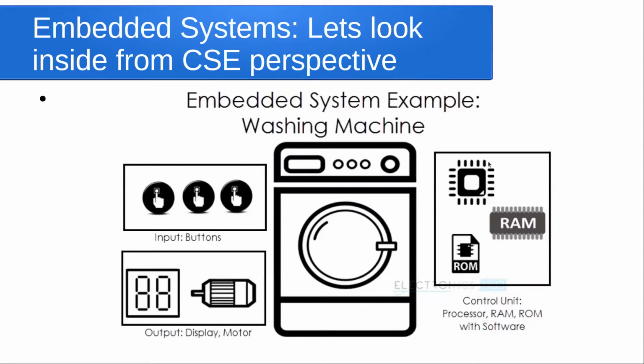Once these inputs are received, depending on the program selected, the processor's or microcontroller's output pins are connected to appropriate display or appropriate output drivers. For instance, if it is a motor that is rotating the drum in here, then the pins for the motion control are connected to the driver of this motor.